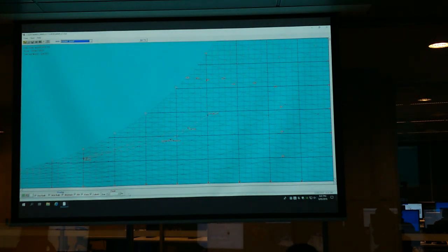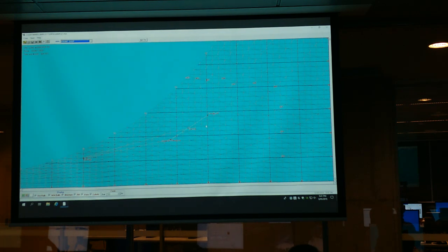you can see the psychrometric chart here. That's what we learned in the class. Remember the typical cycle, a little bit idealized. That's the room condition, 24 degrees dry bulb temperature and 50% relative humidity. And then the outside air condition is also given.